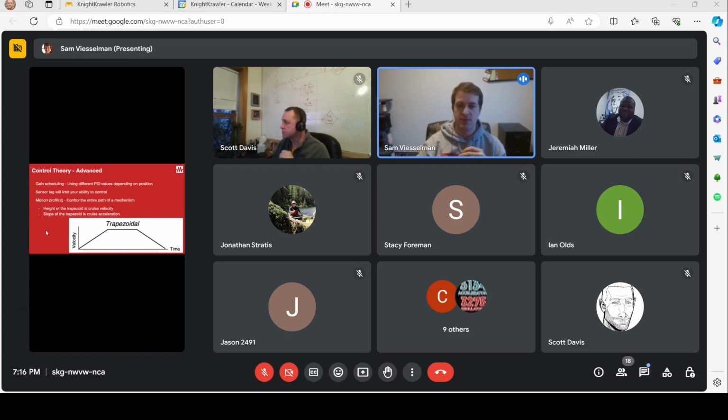And so here's just some advanced concepts. The one is gain scheduling. Gain scheduling is really useful if you have a mechanism that you almost need two sets of PID for. You need one set when you're really close to your set point, and you need another one that's really far away. I won't dig into that too much. I don't think we've ever had to use it, but I know teams have.